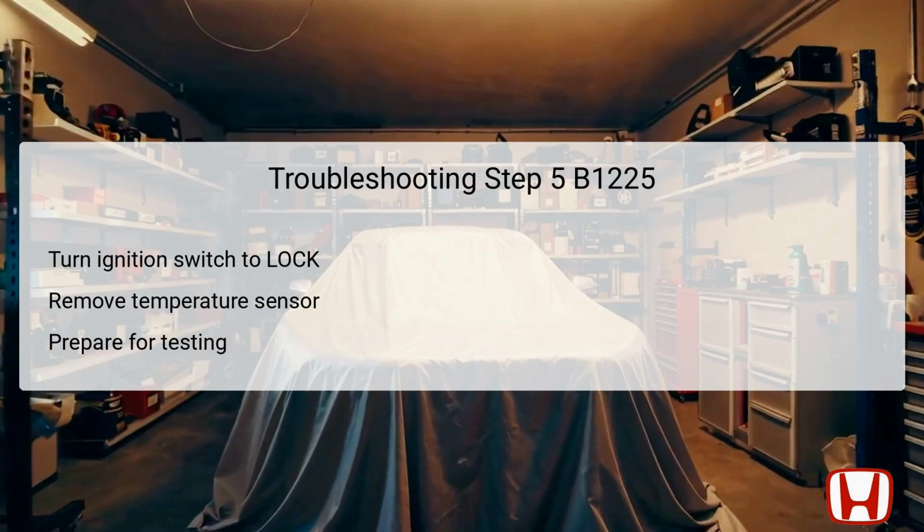The fifth troubleshooting step requires turning the ignition switch back to the lock position before proceeding to remove the humidity and in-car temperature sensor. This precaution is vital to prevent any electrical shorts or further issues while handling the components. Once the ignition is off, carefully disconnect and remove the temperature sensor from its mounting location. It's important to handle the units with precision, as excessive force may cause damage to the sensor or surrounding components.